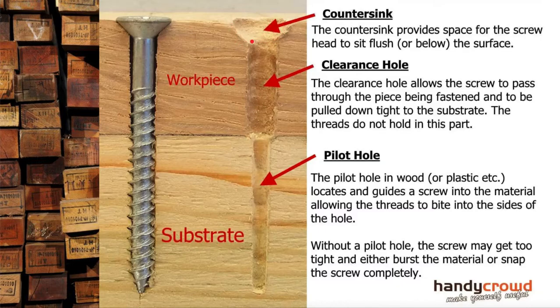Now, I've seen plenty of tradies will go through just with a Phillips head driver and just drill and sort of carve out essentially with a Phillips head. Not the correct way. There's actually specific tools for countersink, and we use those in the workshop quite heavily. You then typically would have a clearance hole. This is going to stop your screw from splitting your main workpiece, your surface workpiece. It's usually slightly larger than the shank and the thread combined. Okay, you can see it only grips in ever so slightly there.